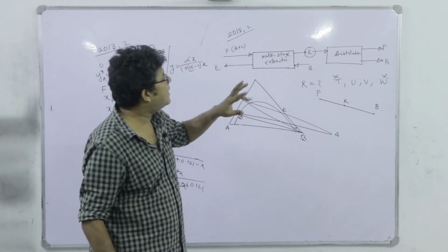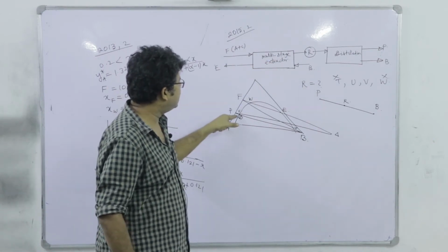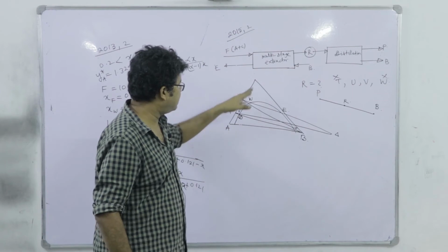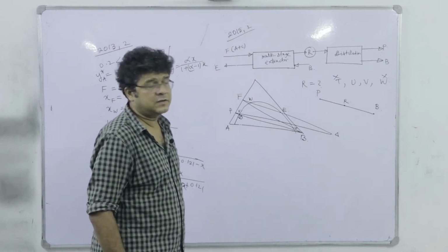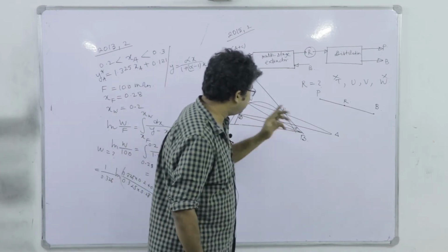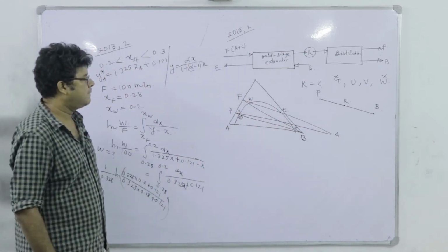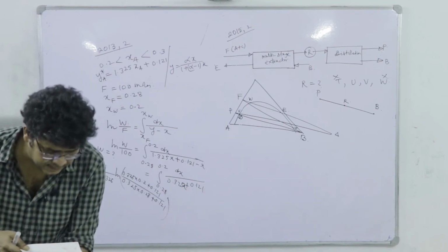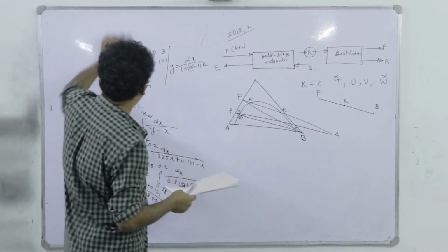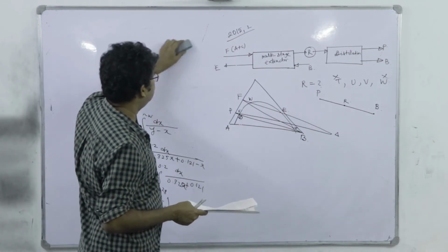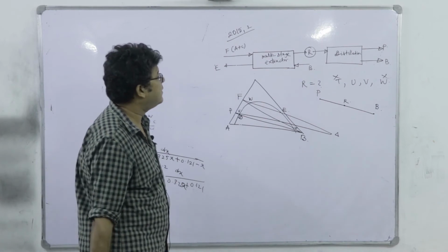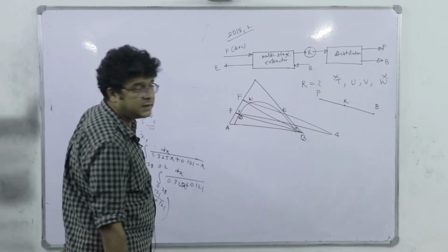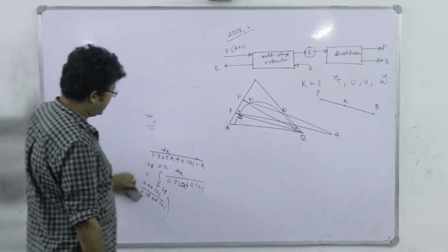So U is the one, and as it is raffinate, it must be on the raffinate arm of the binodal solubility curve, and U is on the raffinate arm, so it is U. So basically, here the problem is, without going by anything, even if I do not know this extraction, simply by looking at R splitting into P and B, we can locate that U is basically the representative point for R.